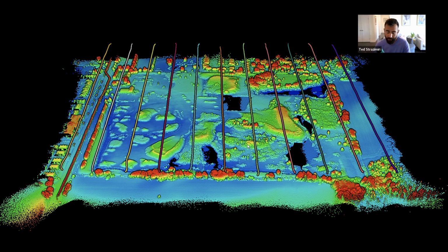The LiDAR scanner is emitting a pulse of light and then it has to detect it. If it's detecting something very faint or something that it perceives as false, it will just discard that information. So as you get higher, that probability of detection starts to decrease, and you have less of a chance to get those second returns, those third returns, etc. So I found that 80 meters is where I preferred to be. It's well above any obstacle. It was a sweet spot between accuracy and efficiency in the field.